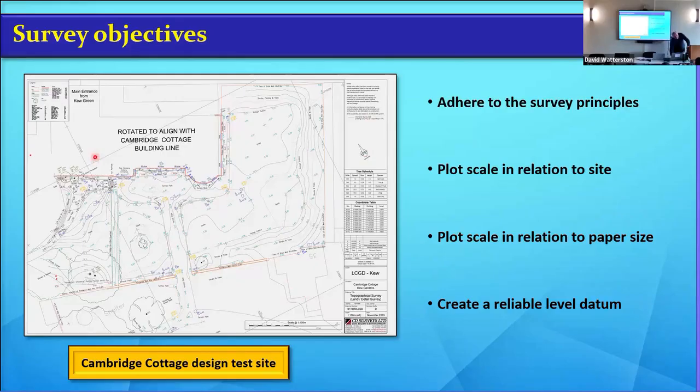But again, if you're doing a design round here, and you want a more defined survey so you can actually put your specific plants in, then you'd want that at greater scale. But you could mention that to them. This area in red, I would like that at 1:20 scale, please, because we need to do design. They might then come back, well, actually, we're surveying this at 100 scale. That's what you're going to pay for. So we will blow up that area at 1:20, but the accuracy will be down to that.